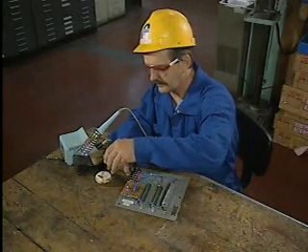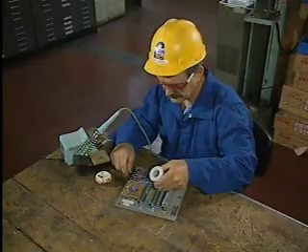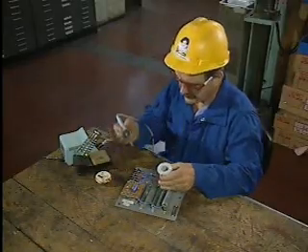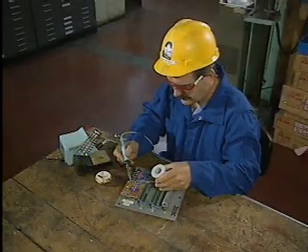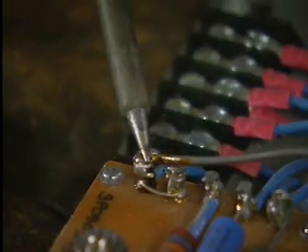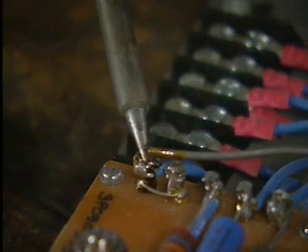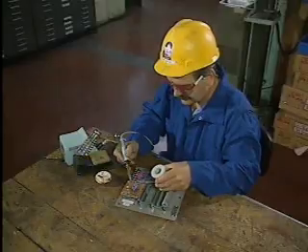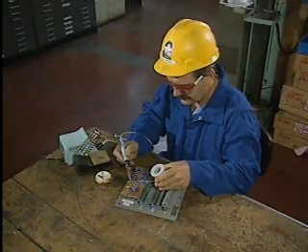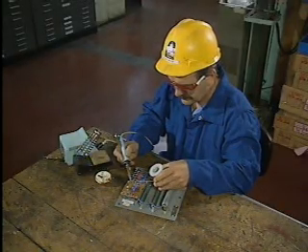If your work involves soldering, you should know that working with a hot soldering iron can be dangerous for more reasons than just the possibility of getting burned. Soldering can produce hazardous fumes, so it should be done only in a well-ventilated area. This will help to minimize your chances of breathing in any of the fumes. Hot solder can spatter, so be sure to wear the proper eye protection.